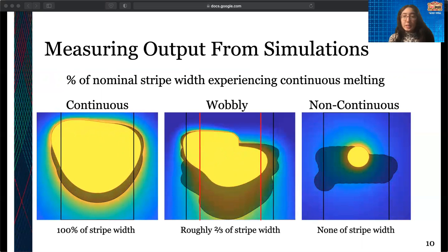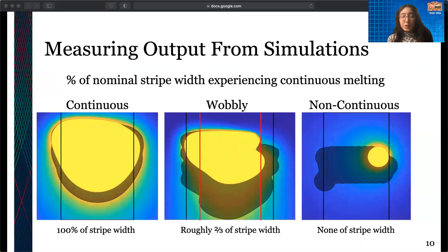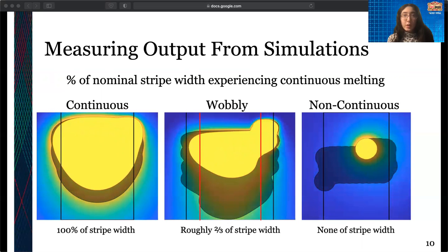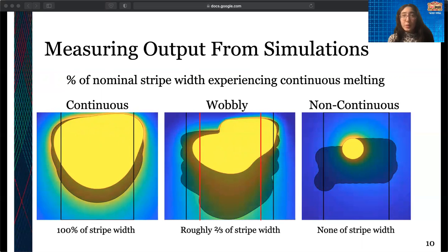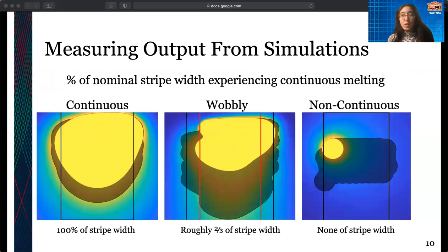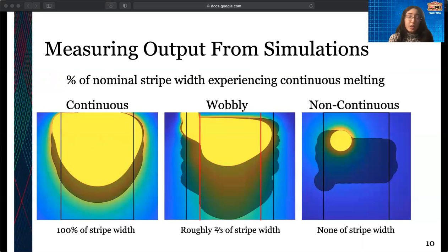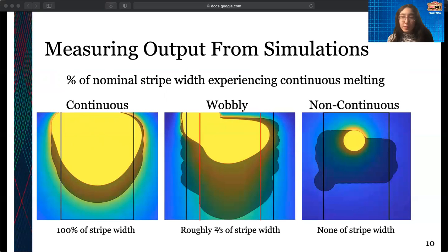Also, on the right-hand side, all of the melt pool solidification velocity directions are horizontal as opposed to vertical from our top-down view. So we get essentially the same outcome as our traditional scan strategy on the right, and the melt pool sizes are not increasing. On the left here, we get a much larger melt pool than we would in our traditional scan strategy, and the melt pool is moving upwards instead of left to right.